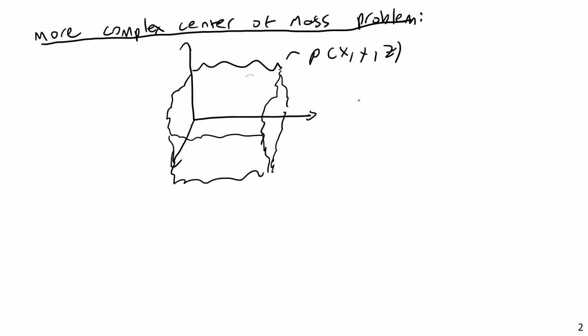To solve this one, you'd have to do it by integration, and you would apply the center of mass formula, or I should probably say integrate the density across the volume to get the center of mass. Not just literally across the volume, you'll have to multiply, basically treating each dx, dy, dz as a small particle and then integrating therein.